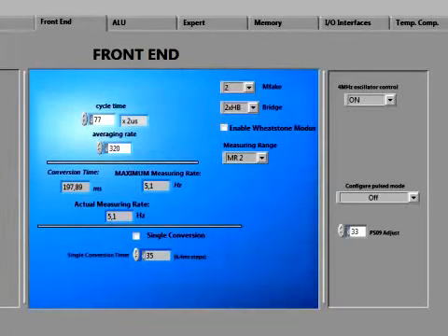The number of discharging cycles needed to make a complete ratio measurement depends on the setting of the number of bridges. Each half bridge contributes 2 cycles of measurement. Thus, a full bridge needs 4 cycles and a quattro bridge needs 8. The number of times this complete measurement ratio has to be measured to calculate one measurement value is given by the setting of the averaging rate configured here.